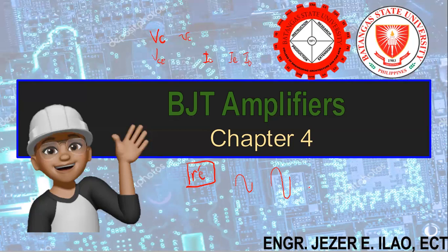So, meron tayong tinatawag na coupling capacitors and bypass capacitors. Okay? So, ano yung ginagawa ng coupling capacitors? Yung coupling capacitors natin, binablock niya ang DC, yung mga DC signals natin. Ibablock ni coupling capacitor yung ating mga DC signals, and ang i-allow niya ay mga AC signals.